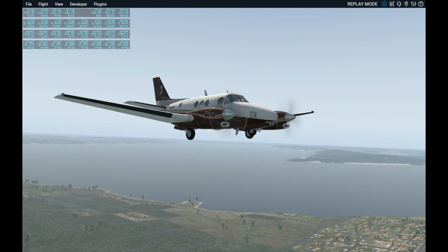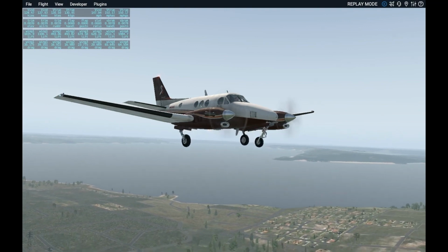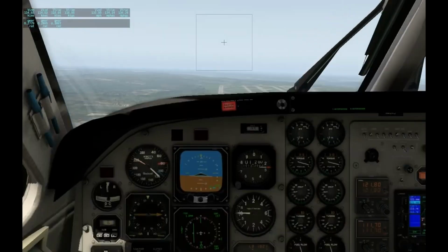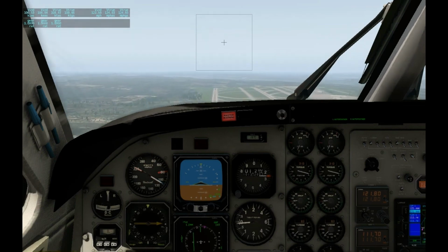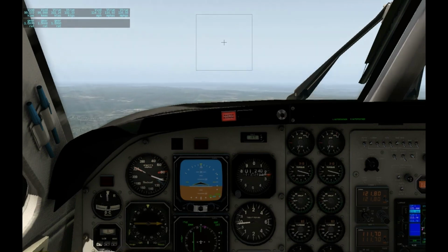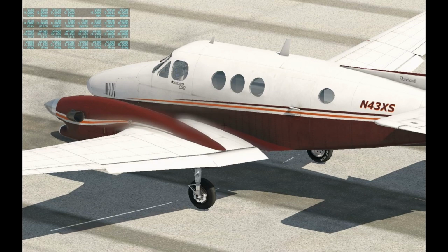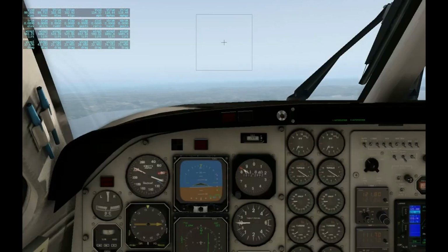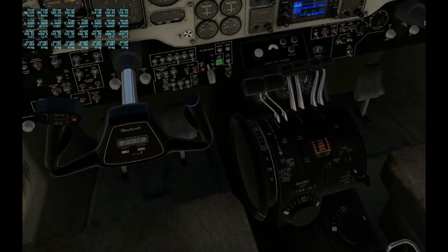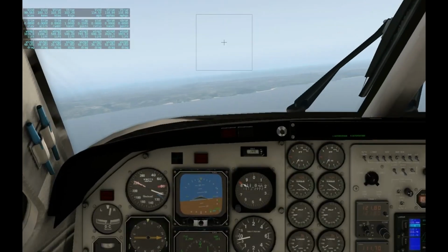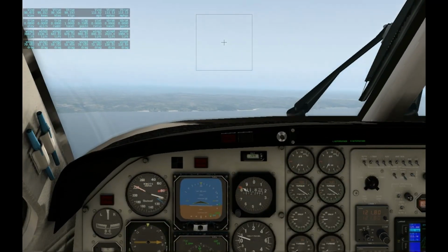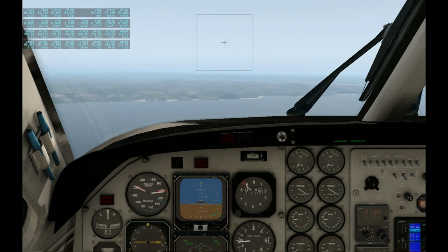In lesson 4 we will now deploy the landing gear to demonstrate the drag component of the landing gear. I've now sped up the video, but as you can see, the aircraft's airspeed continuously decreases after I've deployed the landing gear. And here now we're going to display the flaps. So we're going to engage full flaps, and as you can see, in sped up video again, the airspeed continues to decrease down to a steady 80 knots.